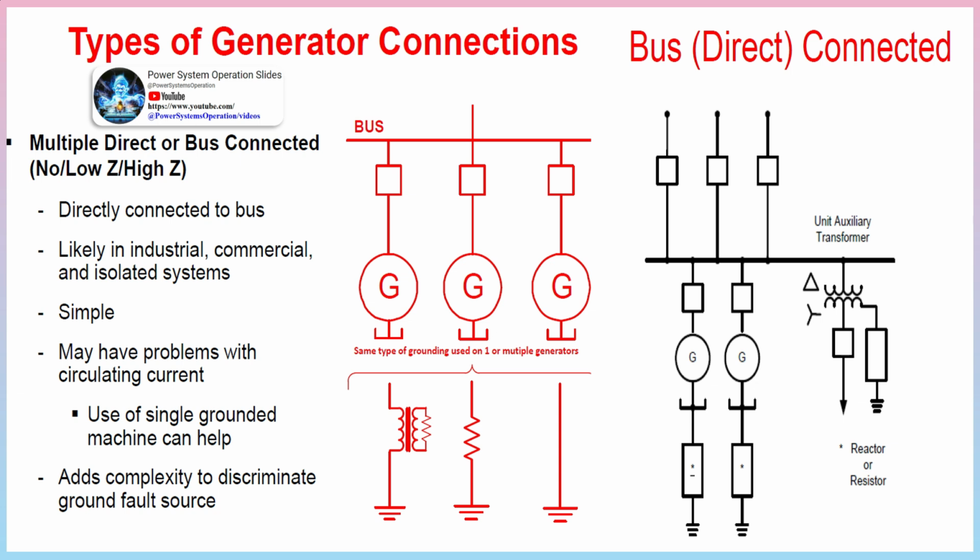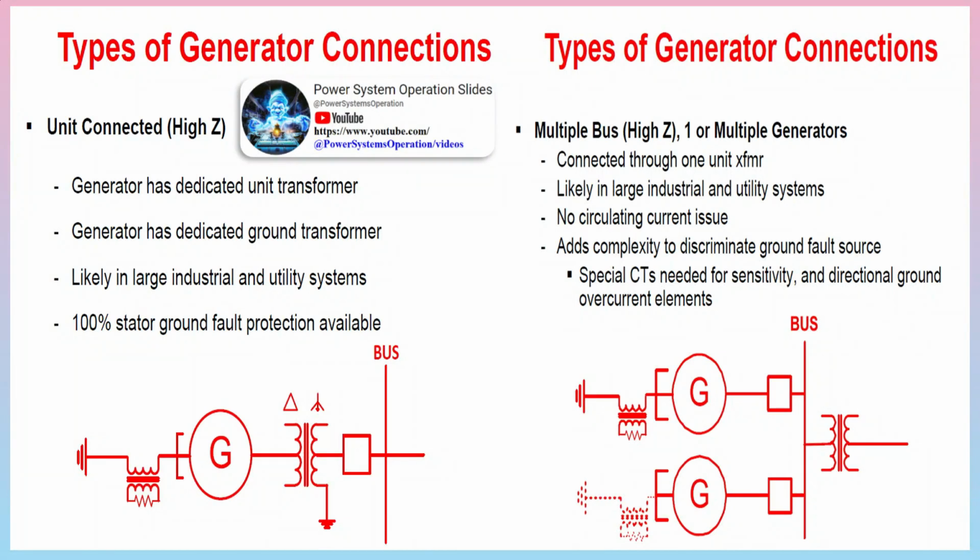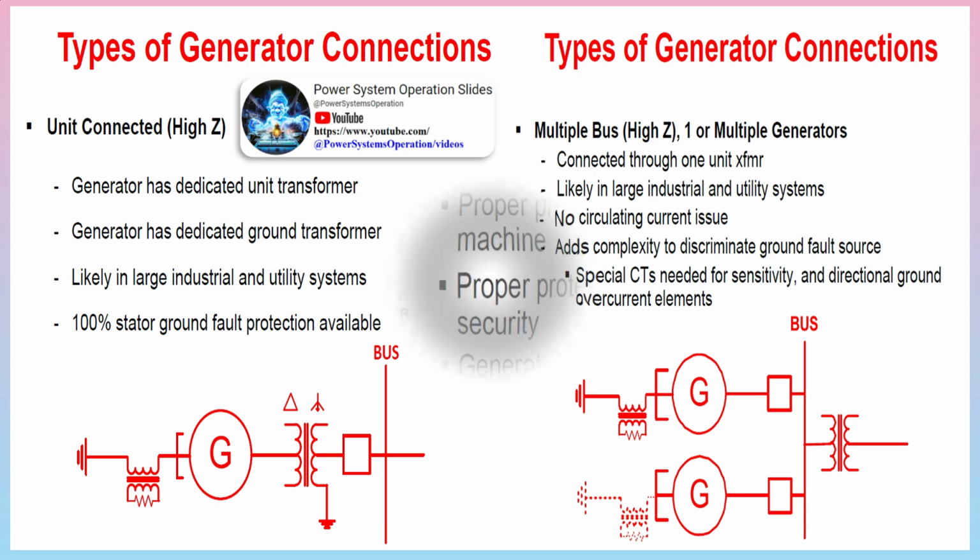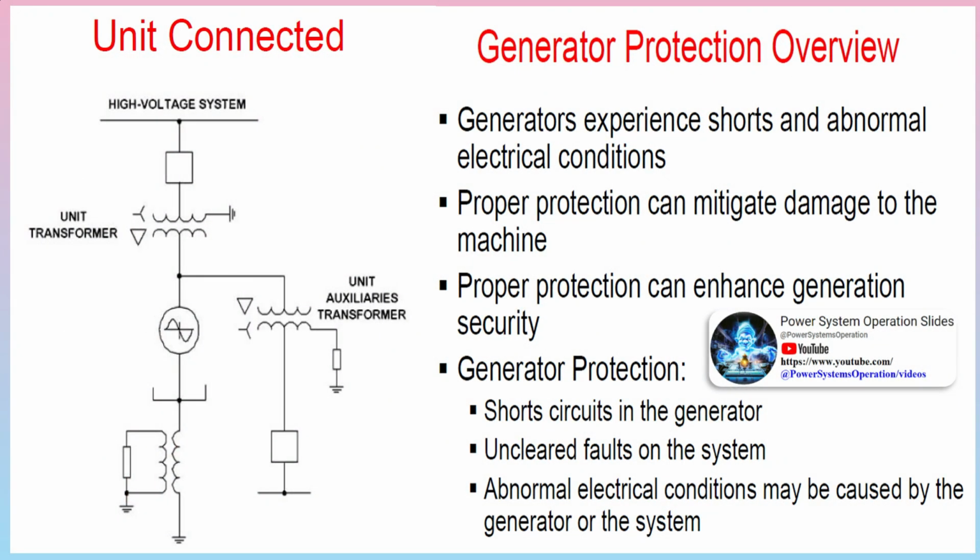Stator earth fault protection. When the stator neutral is earthed through a resistor, a current transformer is mounted in the neutral to earth connection. An inverse time relay is used across the CT secondary when the generator is connected directly to the bus bar. In case the generator feeds power via a delta-star transformer, an instantaneous relay is used for the same purpose. In the former case, the earth fault relay is required to be graded with other fault relays in the system. This is the reason why an inverse time relay is used in this case.